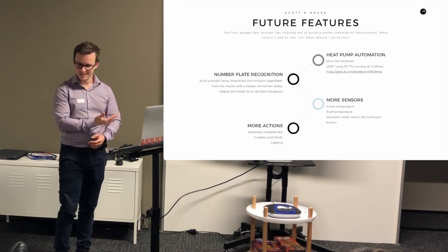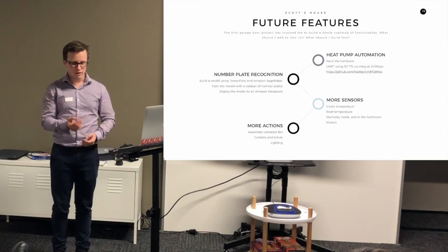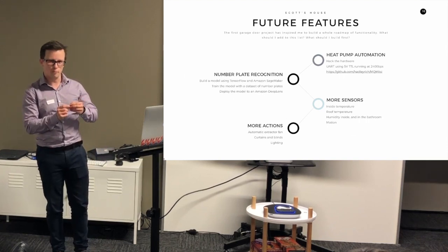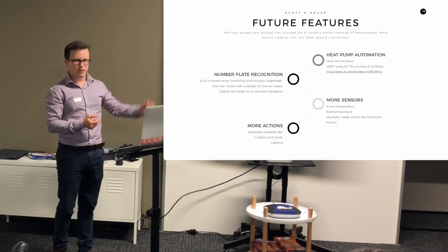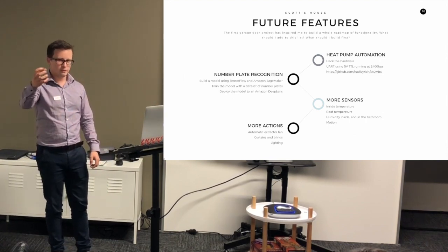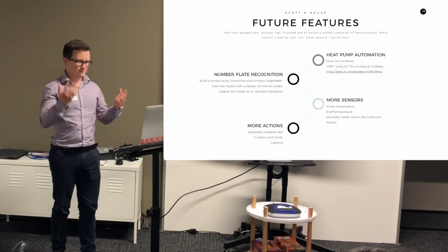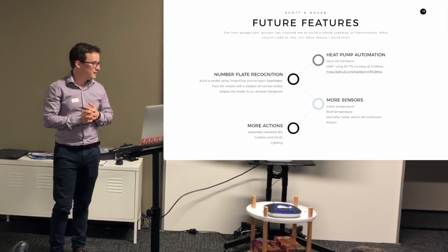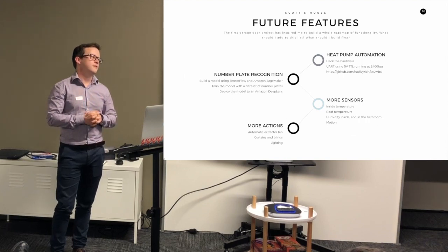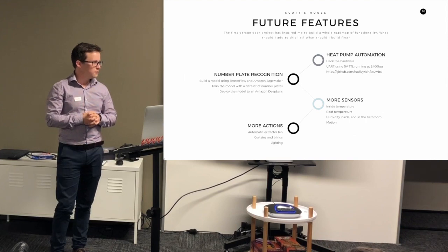Oh, that's lovely. So all I have to do now is make a little riser that has 4 female pins, plug it in, run a Node.js server, stick the Raspberry Pi to the side of the heat pump, and internet connected heat pump. Cool story. That connection seems to be standard across the entire Mitsubishi line, including the big central units. So pretty much, as far as I can tell, any generation that has that has got the one protocol.